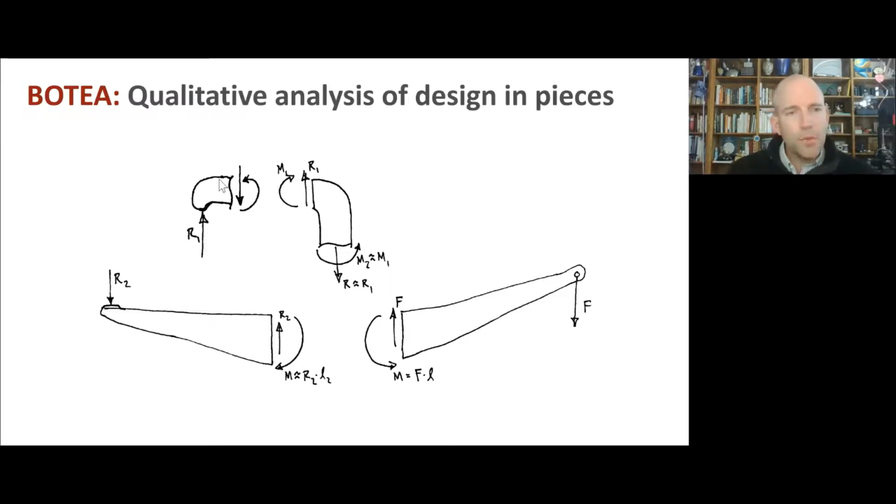And then we need to move quickly to a very tall cross section here. Why a tall cross section? Because sigma equals My over I, and I, if I say have a rectangular cross section, but it's always true that the height has a disproportionate effect, I might be 1/12 base times height cubed. So making the thing tall makes the area moment of inertia big fast with the least amount of mass.